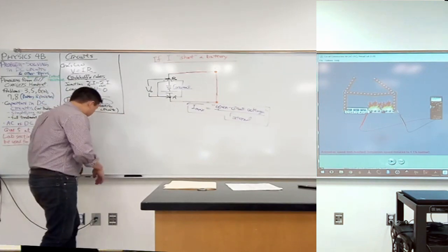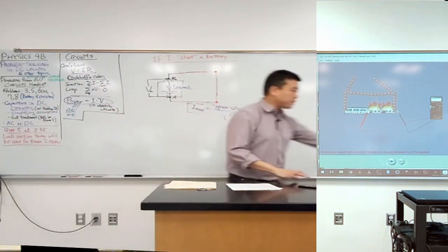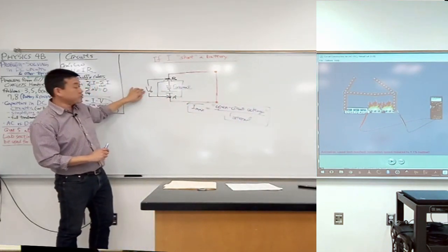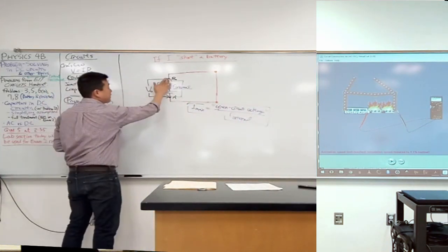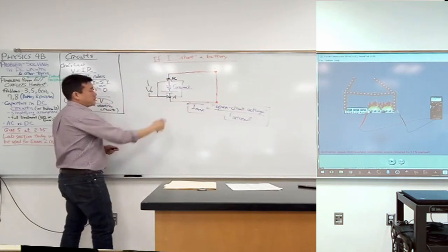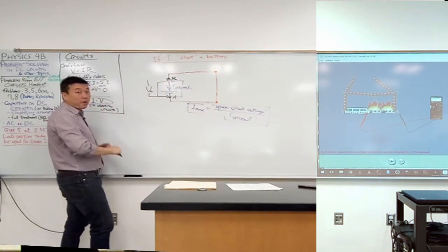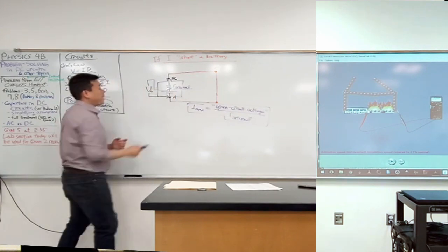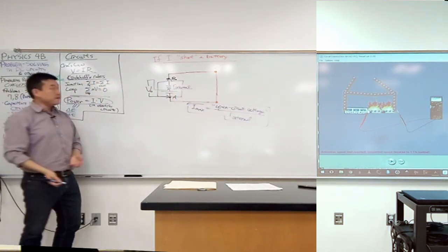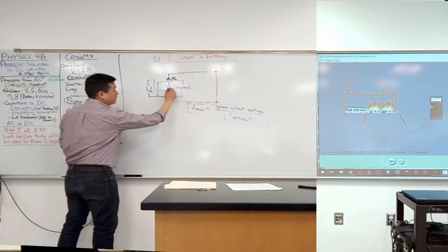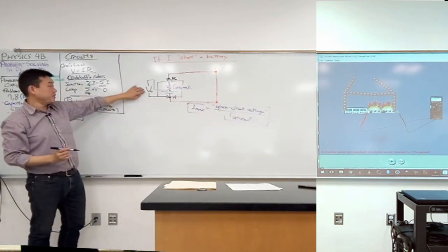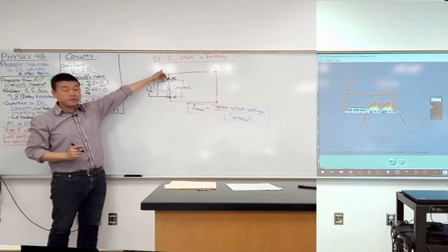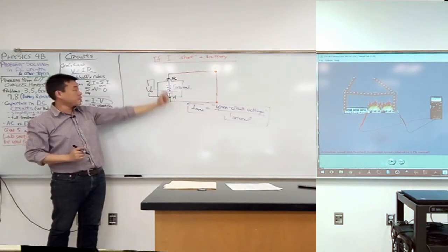The thing that we say about the battery no longer says that between the two physical terminals of the battery is the voltage V naught. Instead, it says between one of the terminals and the other point, which is internal to the battery and we can never access it, this voltage difference is V naught. But before you actually get the measurable voltage here, there can be additional voltage drop if there's current flowing.